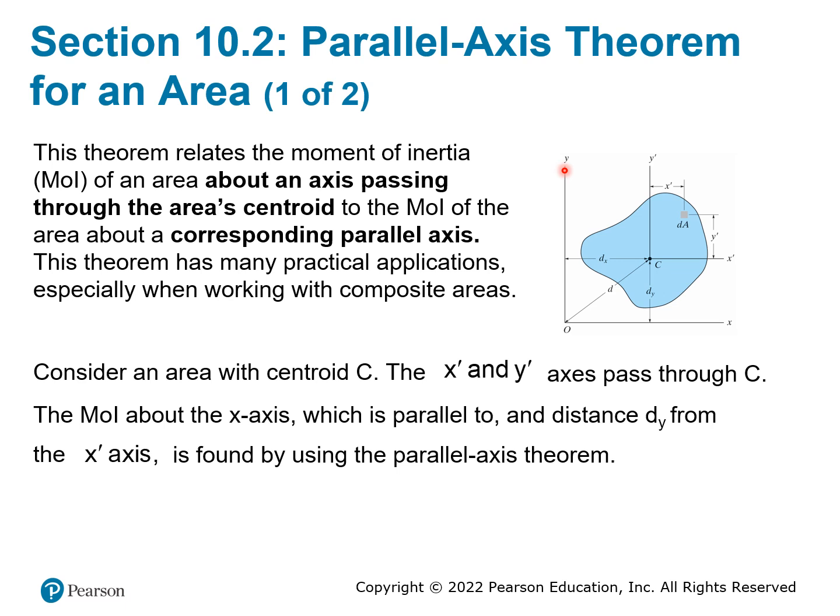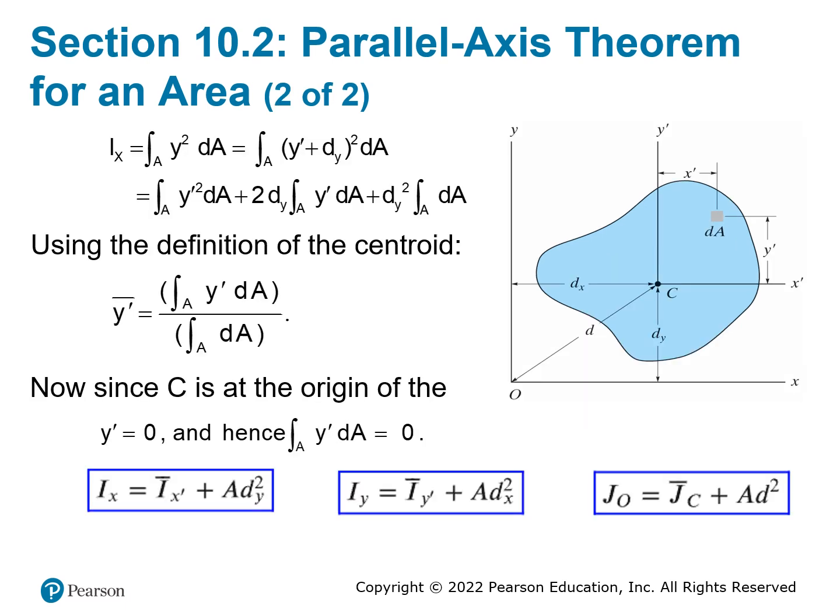And when we find the moment of inertia, if you're not rotating about the center of the object, but about somewhere away from that, then you have to use the parallel axis method. This method requires choosing an axis which is parallel to the axis through the centroid. And you have to pick the axis. So we're looking at how the shape is rotating about the axis that you choose.